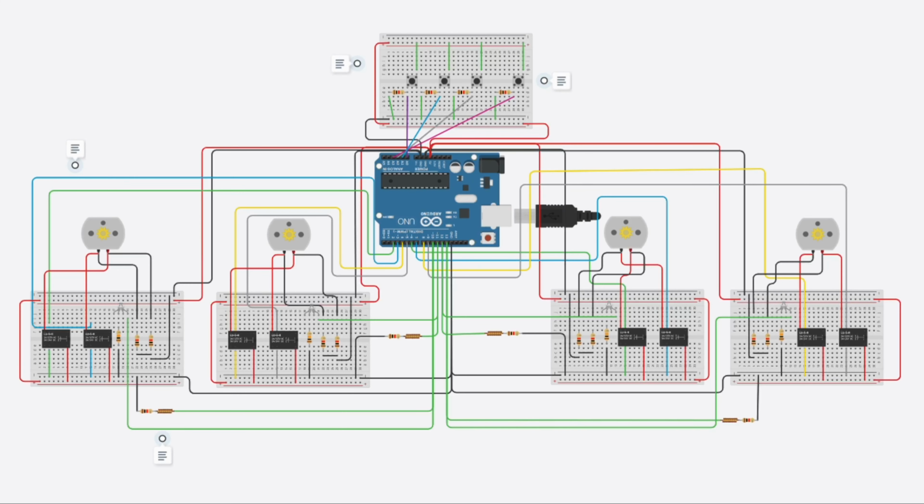The controls for the smart bin operate by using an Arduino Uno to systematically energize then de-energize solenoids and linear actuators. This simulation was produced using Tinkercad and unfortunately was unable to simulate a few components in our design. The linear actuators are substituted by DC motors, and the inductive coils represent the solenoids. The push buttons above represent digital input that would be produced from the sensors, i.e. the load cell and the camera.